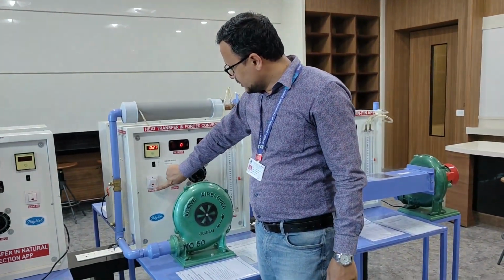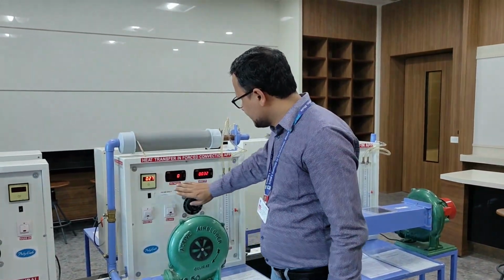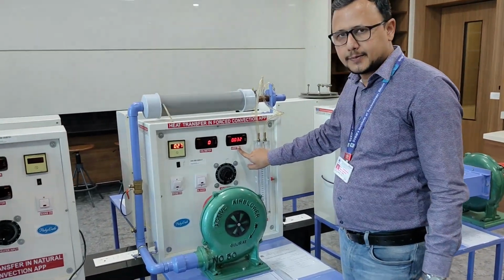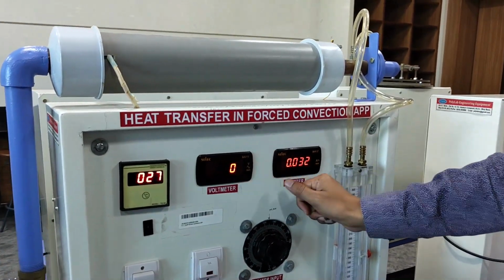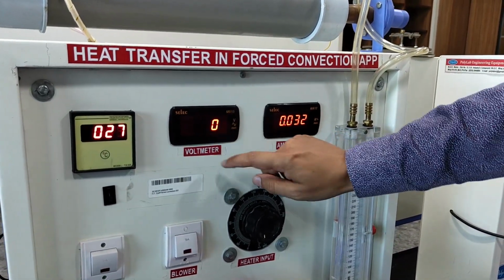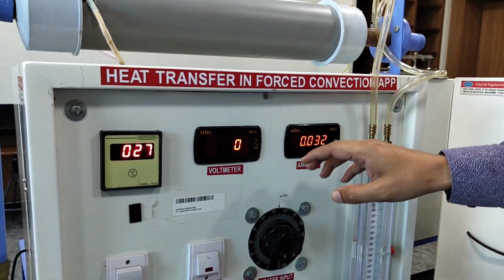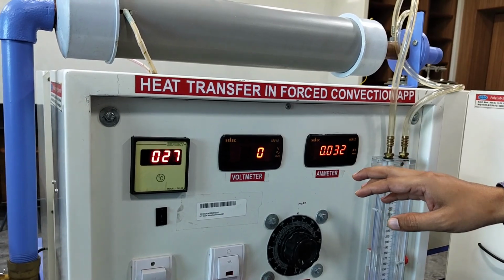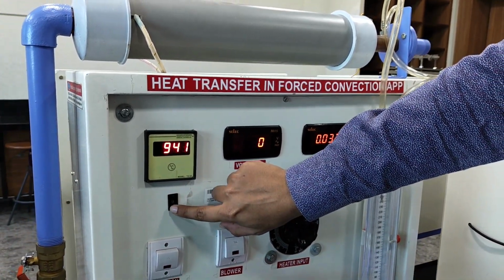Once you switch on the mains switch, there will be temperature indicator which will be switched on, the voltmeter and the ammeter. The amount of heat supplied will be the product of voltage and the current. Why? Because this is a single phase setup. Electricity is supplied in the single phase, so product of voltage and current will give you the amount of heat which is supplied to the experimental setup. Also, we can change the temperatures.